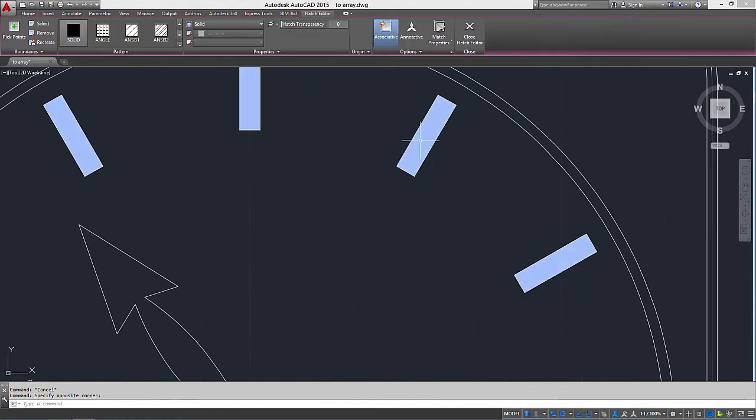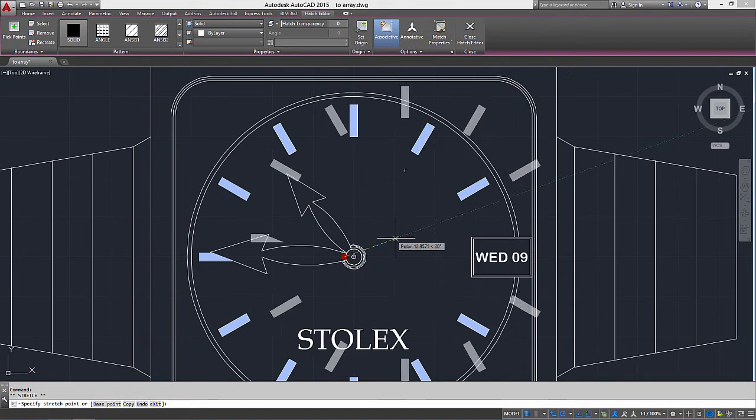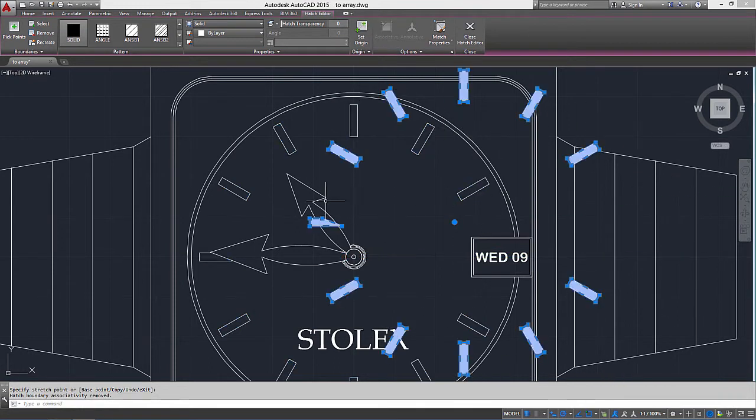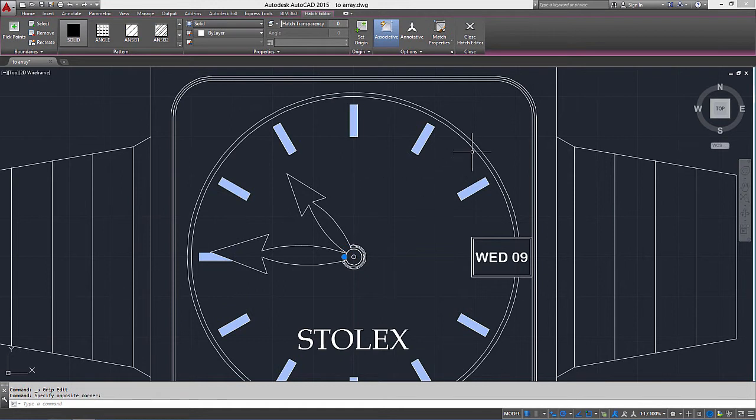Let's see whether it's picked the hatch. No, it's created a hatch which is kind of centered there, but what it's done is added all these boundaries up together. It's not created individual ones because we picked individually, which makes sense because obviously if you're hatching certain objects, you might want to have them grouped. If you don't want these hatches grouped, then the way to ungroup them is, now I'm just looking around because I know what it is, but I'm seeing whether they've actually created anything else. Under options, separate hatches, there it is.